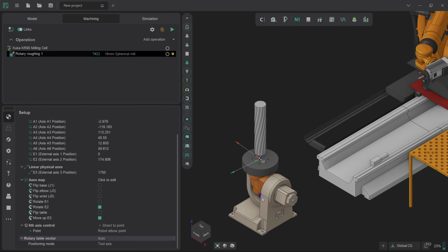At the moment, it defaults to going vertically down, which is not really what we want. We want it to correspond to the x-axis. So I'm going to go with positive x, and we can see that this blue arrow here, which conveniently goes orange as soon as I highlight it, is now oriented to indicate the correct direction that we're going to bring the machine tool in from.